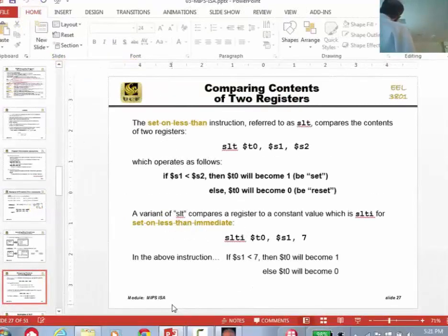It's called register mode. It takes in 2 register operands, and the result goes to a register. If it's immediate mode, it takes in 1 register as an input, and the other number is a constant, 7 or 1. We call it immediate because when we look inside the circuit and we design it, coming very soon, this value is immediately available. I don't have to go to the register and look it up. It's immediately available. It's always 7.